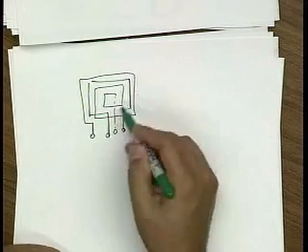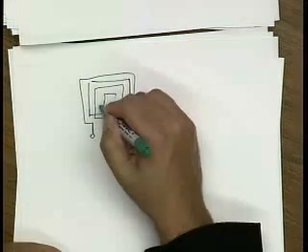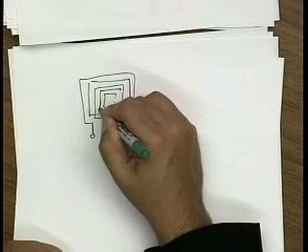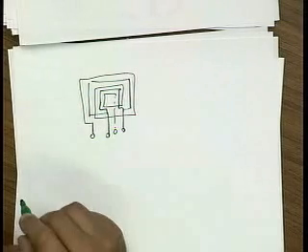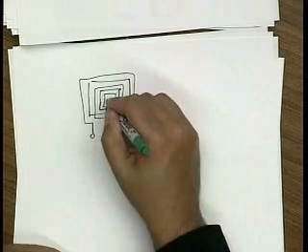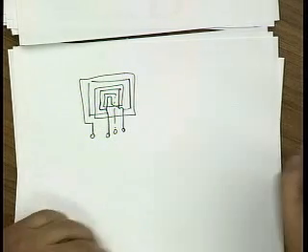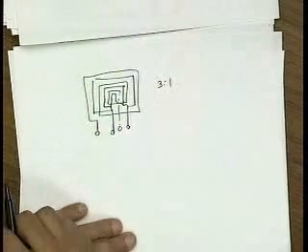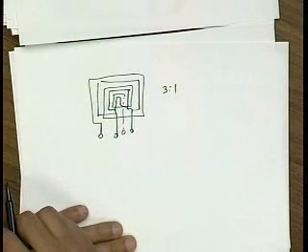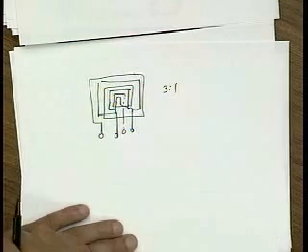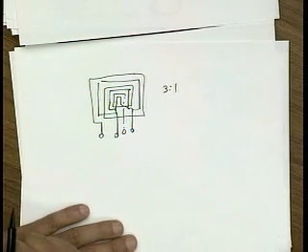So this is just 1 turn. So this is a 3-to-1. But I might as well put another turn in parallel to lower the resistance, and maybe even a third turn. So this is like a 3-to-1 transformer. Differential flux still cancels, still lossless. No, you don't get that benefit. A 1-to-1 will only give you that benefit.